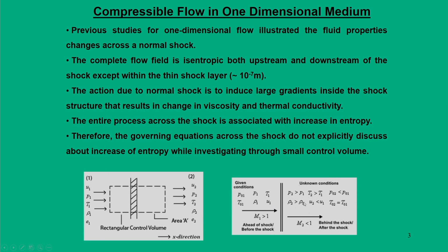When you derive these relations for entropy change, we do not explicitly talk about the increase in entropy, because the enhanced pressure and temperature jumps have already ensured that entropy will increase. But in this process also, we say that the entire imaginary duct which contains this normal shock is adiabatic in nature. In fact, there is no heat addition in this process.